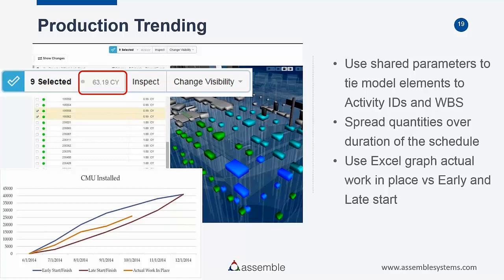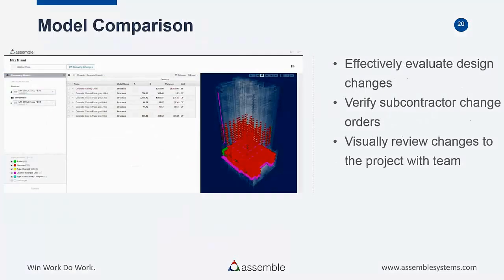So we're going to use that to track our production of basically everything that's poured. We're going to make sure that we put an install date on basically every deck, every column, every beam that's in that building, so we have a really good idea to compare our delivery tickets to our actual work in place.